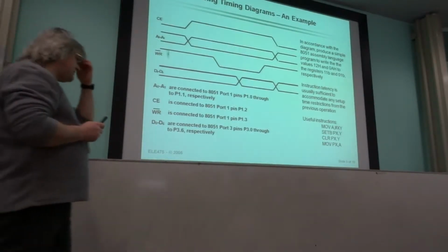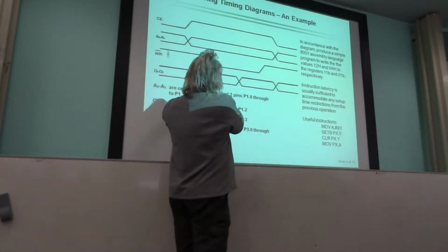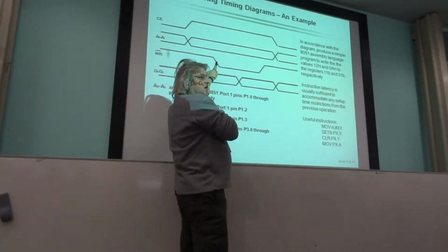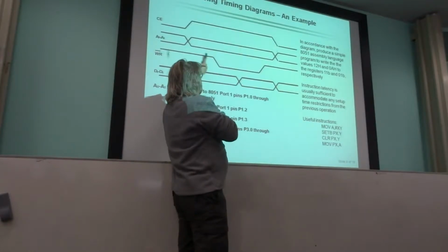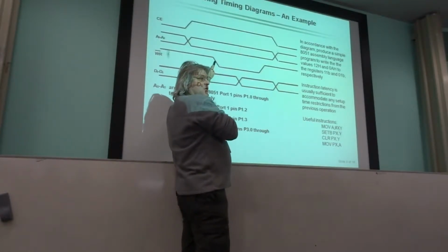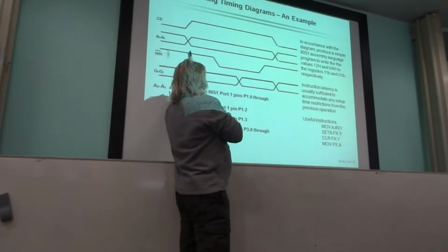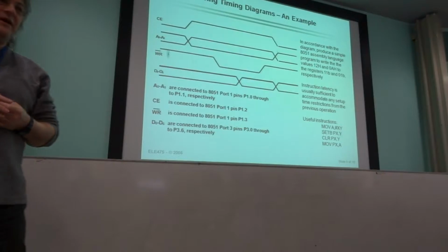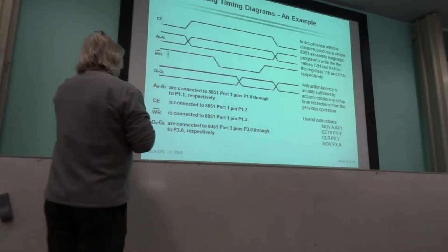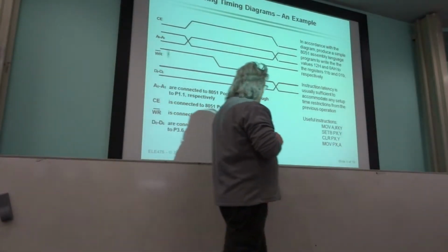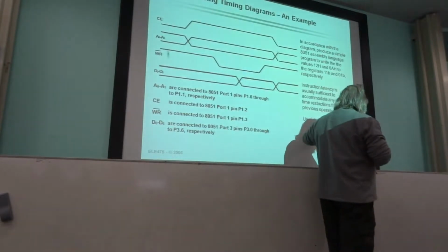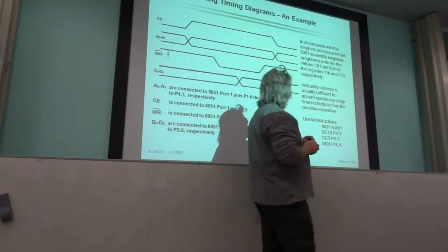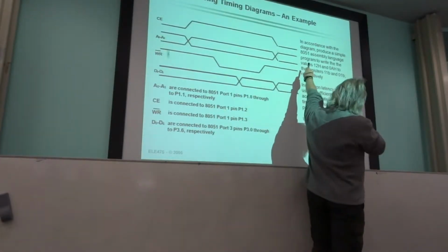In the real world, it may be, for example, from the time that the address bus is stable to when this write signal has gone low here, you would have to check in the data sheet whether there is a minimum time, a kind of setup time, that you need to be aware of, so that you don't perform this transition too quickly. But we're not going to worry about that. We're just going to try and get the sequence right. Also, we're being told that there are these useful instructions that we may wish to use. And I'll read what it says up there.